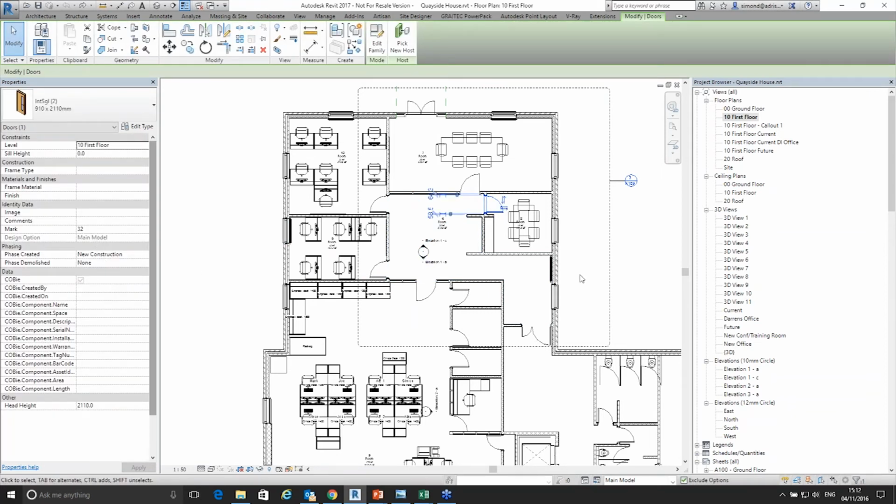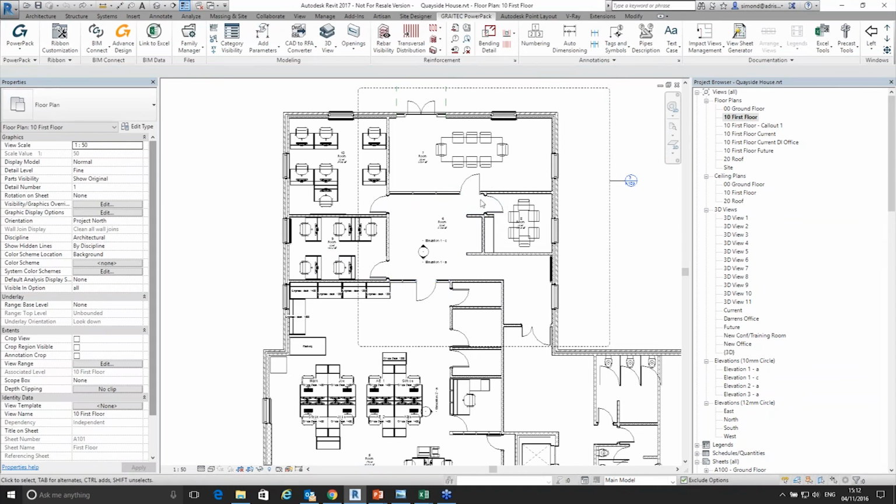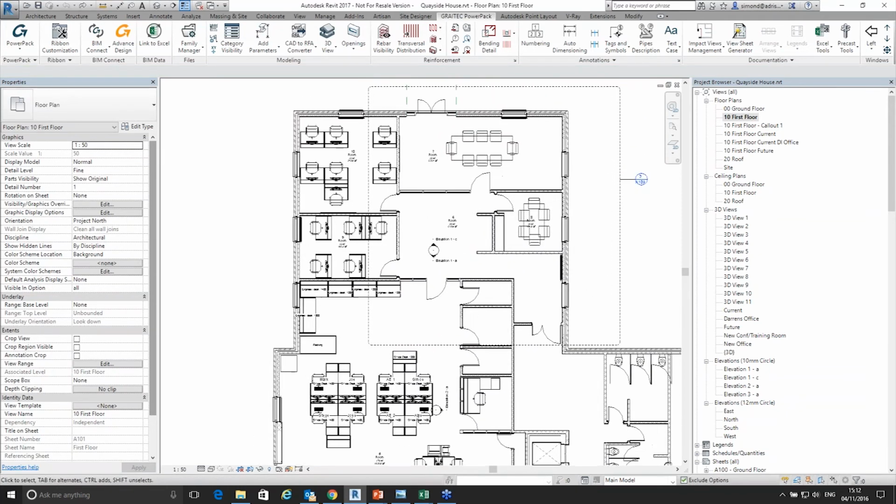I can suppress them, it will still register the warnings, and I can still go to my warnings dialog box and find them, but at least it's not disturbing me whilst I'm working. If we do find duplicates, I have a drop down that allows me to control how to deal with a duplicate if I'm not allowing duplicates. So we can erase the existing duplicate. Basically it'll just erase that value. It's not the family, it's the value, and it'll set that to blank.